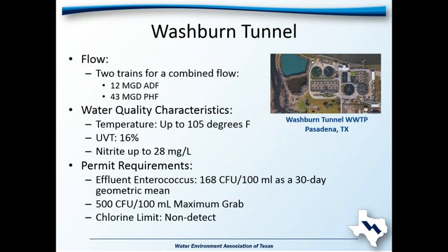Here's the wastewater characteristics. At the time that we did this, it was going to be the largest peracetic acid disinfection system in North America. The key things to look at here that really drove our decision to go to peracetic acid are the very low UV transmittance and the relatively high peaks of nitrite, and we would get some kind of nitrate lock in our